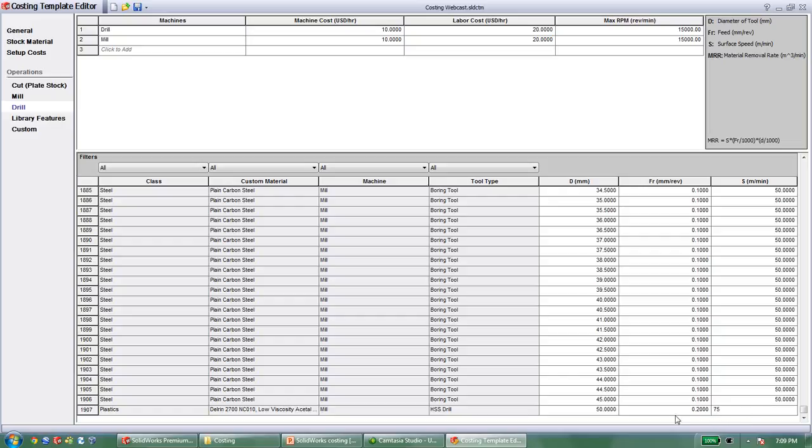That's pretty much all it takes to add a custom speed or feed to get your custom material removal rate. Knowing this, I would go in and change all these settings to more accurately represent what I commonly do, so that when it calculates material removal rate, that information is actually accurate. Again, costing is one of those tools you'll want to go in and set before you start trusting the values of it.